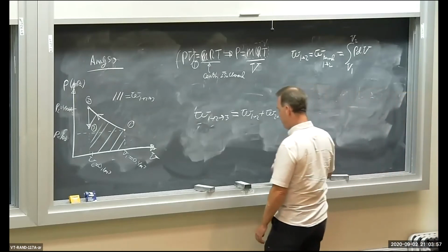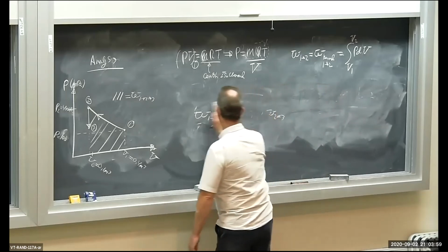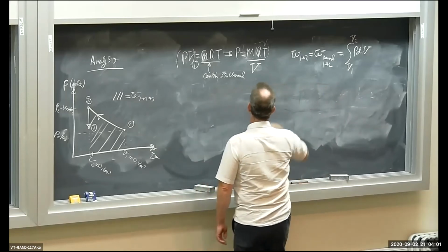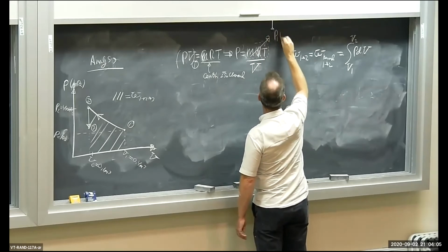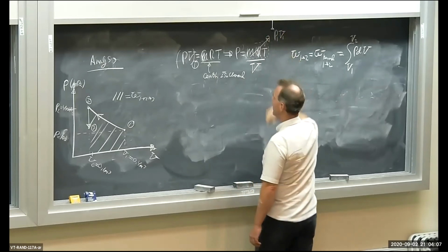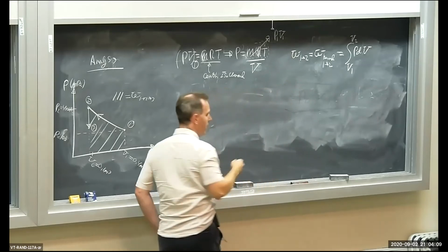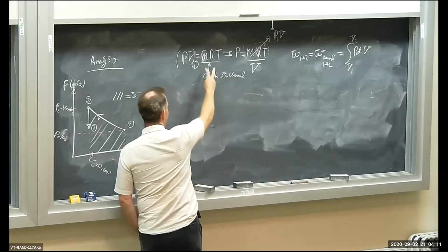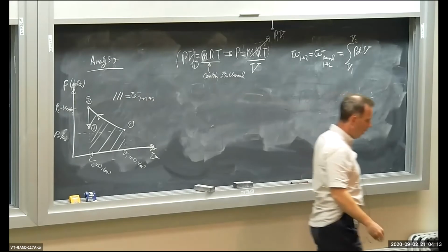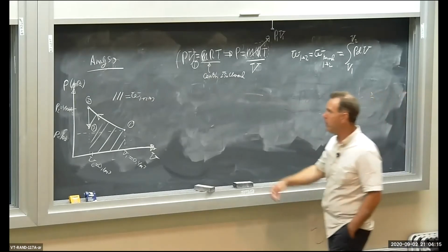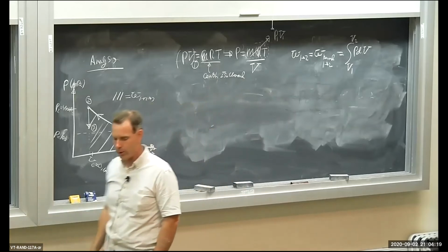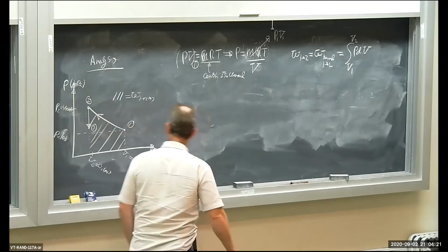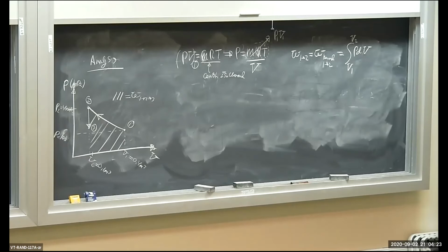So I'm going to substitute P1 V1 into MRT. Because it's an isothermal process, MRT is constant. What is MRT actually equal to? It's equal to pressure times volume anywhere along the path 1 to 2. I do know pressure and volume at state 1.